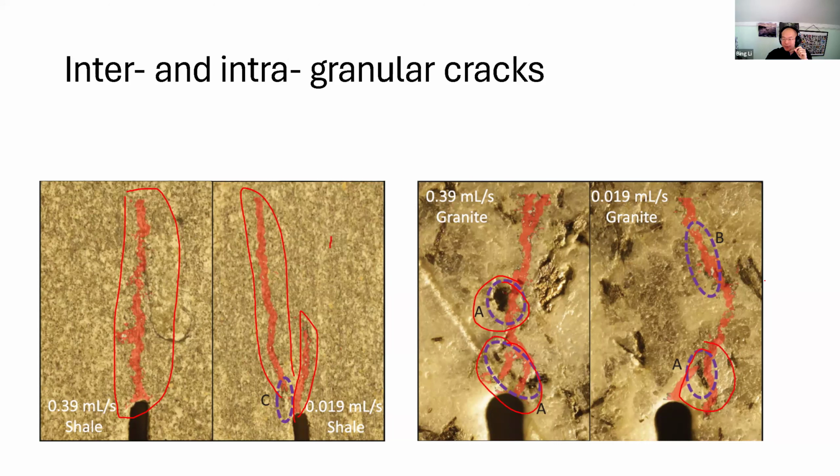which is quite cool. So in the case of this granite, for example, it actually avoids this dark grain, right? You can see, there we go. We can see that these 2 branches of microcracks actually don't connect, and they're separated by this dark grain here, which I presume is a much tougher material that these microcracks cannot propagate through. And in a lot of cases, for example, here as well, it tends to follow this intergranular crack around tougher grains, at least from what we can see from the surface of these materials.